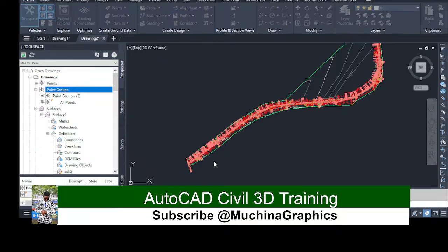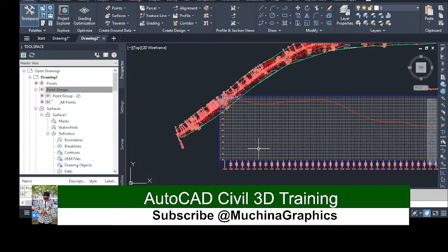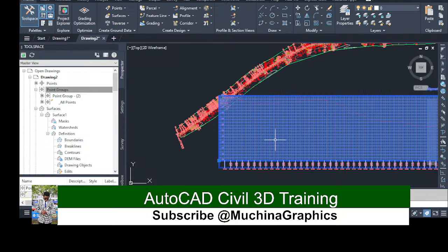After I add this, I will draw profile, and then here I need to click next, next, next, and next again, and then I click create profile view. So this cursor will appear, and I'll choose where to place my view. So I can choose here like that, but for this one we have made a mistake because it will collide with our drawings. So I'm going to select this one again.